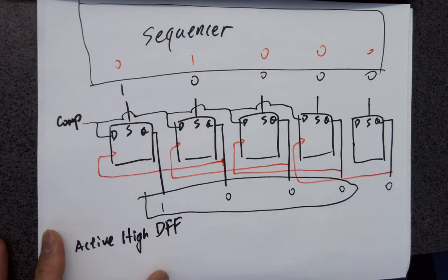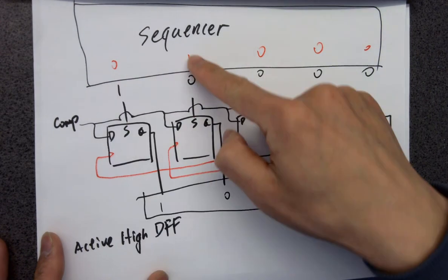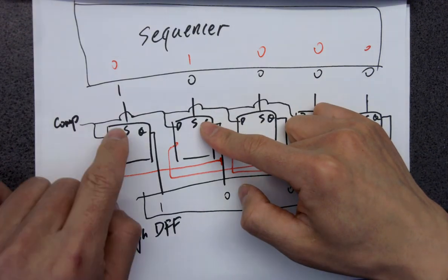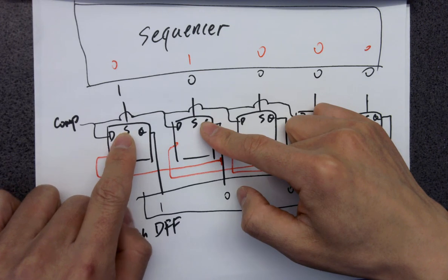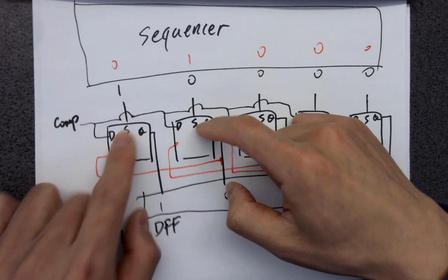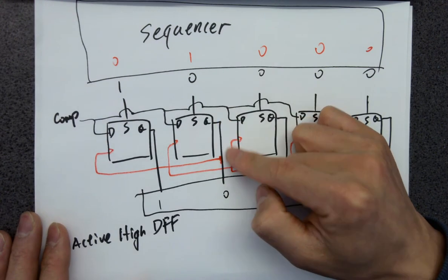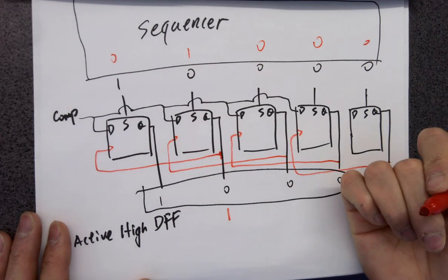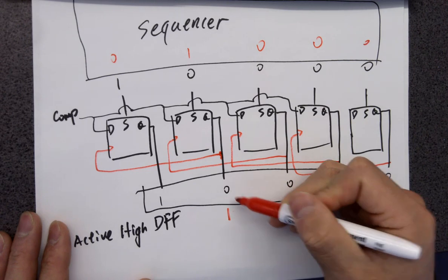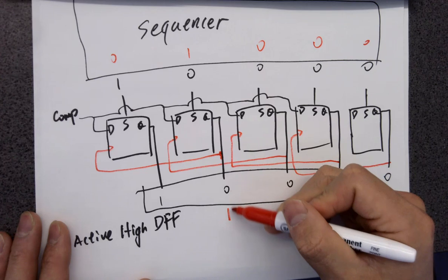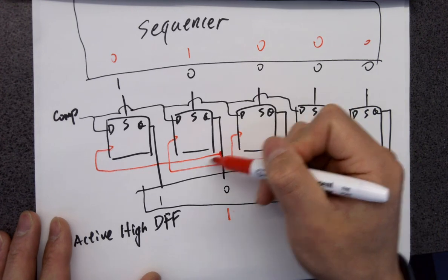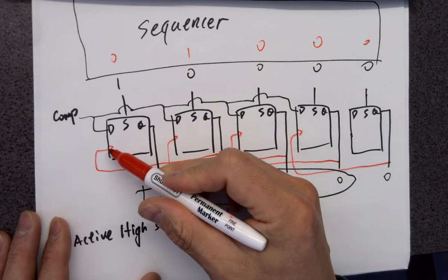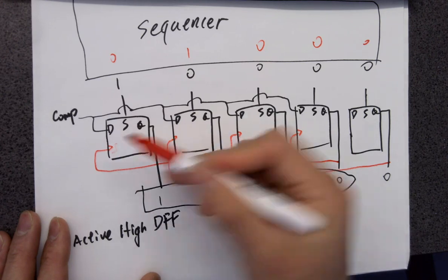So what's happening here? If this 1 shifted to here, this will be set, and this will not. Okay? If this is being set, Q becomes what? 1. It was 0 and now it's 1. So you can see there's a rising edge. And that 1 is shorted to the clock of the previous stage. So the rising edge is actually given to the clock pin of the previous stage. So you are seeing a rising edge over here.